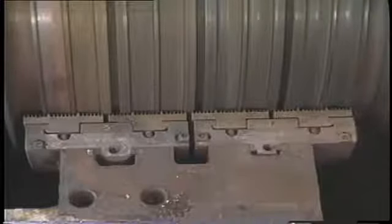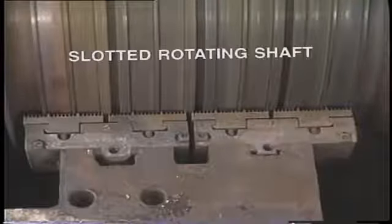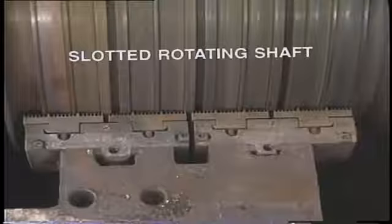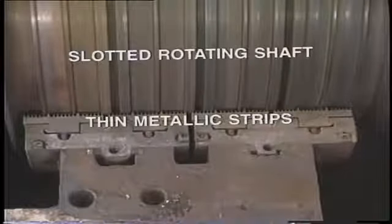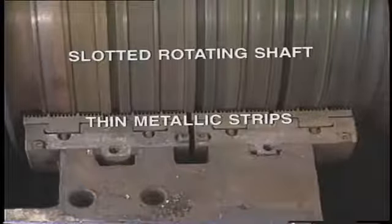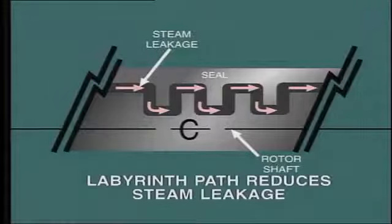This is achieved by the use of a labyrinth seal. The rotating portion on the shaft is slotted like this, while the stationary portion consists of thin metallic strips which are pressed into the rotating grooves by very light spring pressure. The resultant labyrinth path considerably reduces the leakage of steam out or air in.